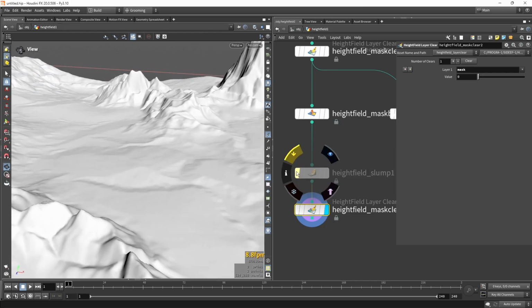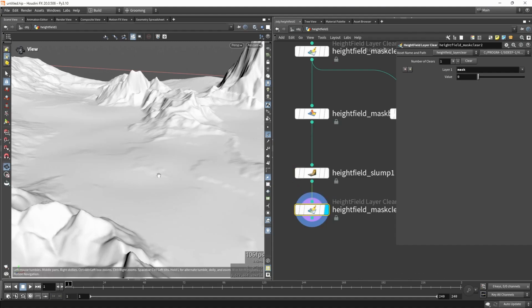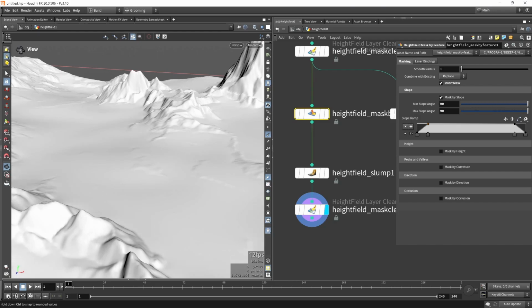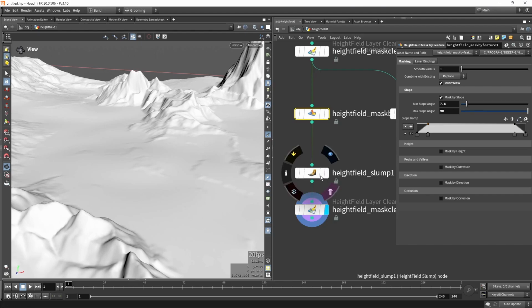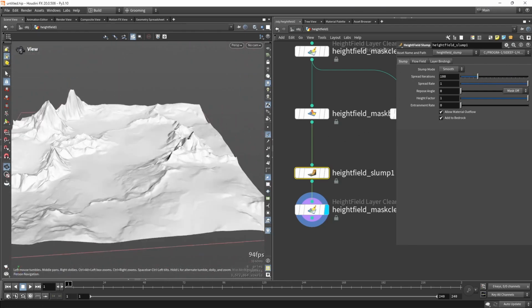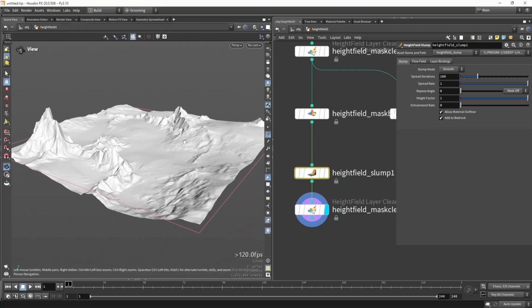So if your terrain is too noisy or too rocky, like here we have quite nice rock shapes and noises, but sometimes you want to blend it with dirt. And this is again controlled by the mask, so I can always here control this mask, but based how much noise or dirt we want to have on the terrain. So I can control that nicely. We can also here have some iterations about how it should go, and you can play around with that. So I'm going to leave it as the default value. So now we have a terrain like this.